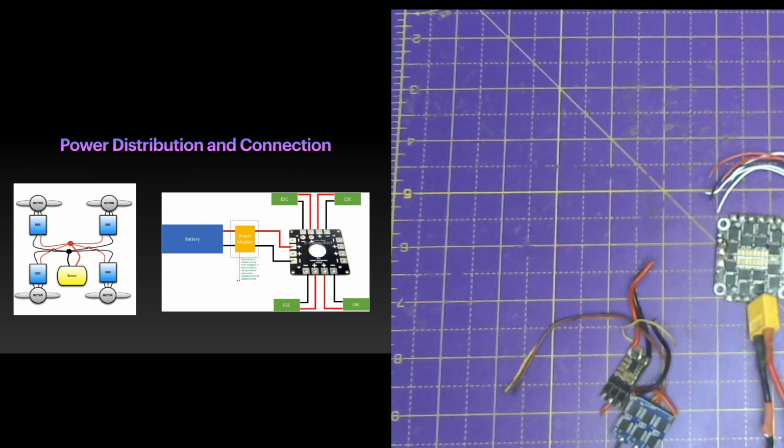And because we are talking about quadcopters, we have 4 motors, we have 4 ESCs, but we only have 1 battery. So we need to share the battery to all the 4 motors, and this looks quite ugly if you do it by soldering and connecting all together. So that is why we use something called a power distribution board. This is nothing but a small PCB. Over here I connect my battery, and the battery is distributed using this PCB, and each ESC can be connected to one particular port. So this is a small component which you can use. It's called a power distribution board.